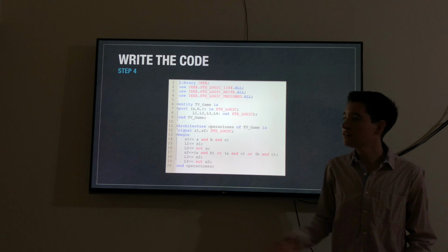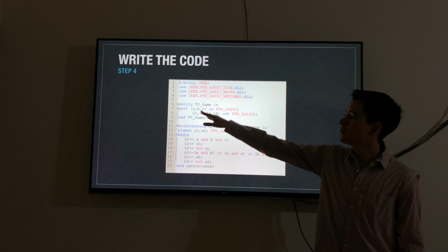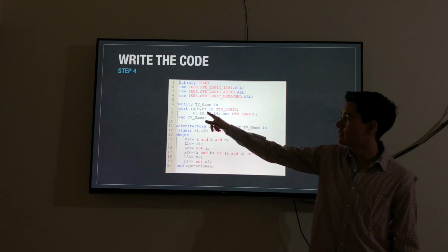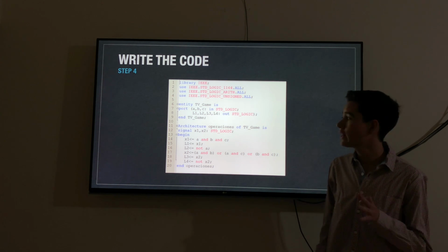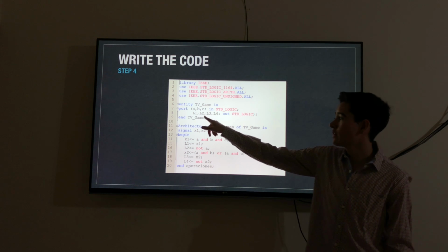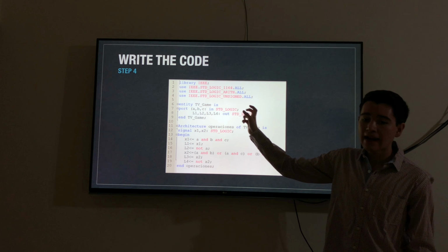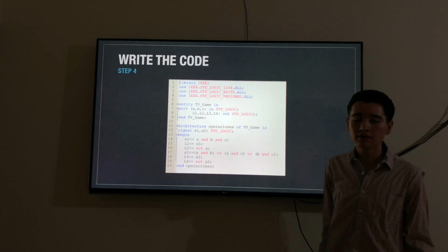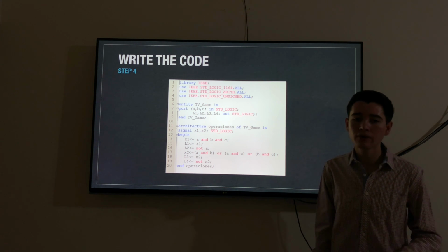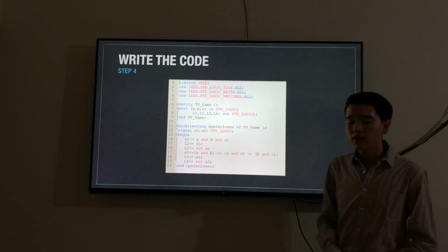The structure of the entity is entity, the name of the project, the ports that we are going to use, in this case 3 input ports that are A, B, and C for the 3 persons that we have, and the 4 output ports, led 1, led 2, led 3, and led 4. The type of these values is logic, because we are going to work with logic values. And then we end the entity.